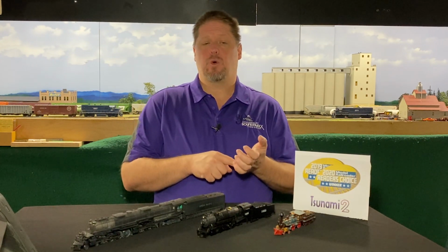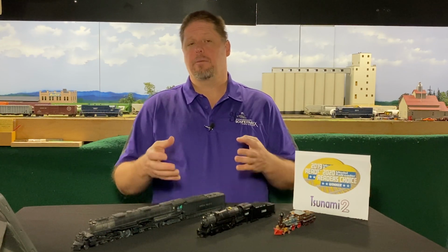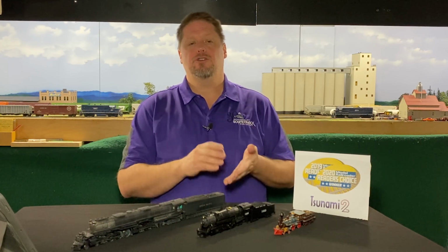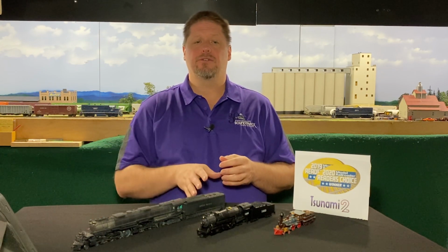Now, when you press the F12 on your throttle, now your decoder is going to transform and go into automatic train brake mode. And you're also going to hear the compressor start working to charge that train line. Now, this compressor will run for about 30 seconds. In the real world, it takes about 10 to 15 minutes to charge the train, depending on how long the train is. Now, this way you get a better experience of what's actually happening. So once you tie into the train, your F12 is on, you start running. When you press the F11 now, you're actually going to hear the sounds of the automatic or the train brake. You're going to hear the air reduction out of the locomotive.